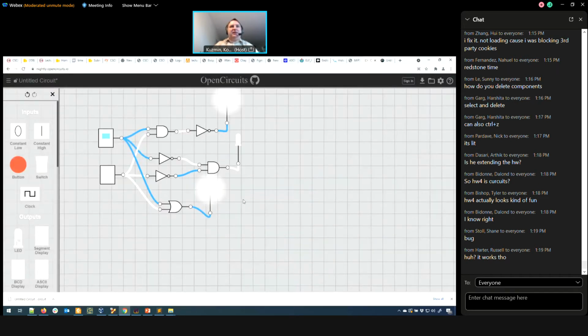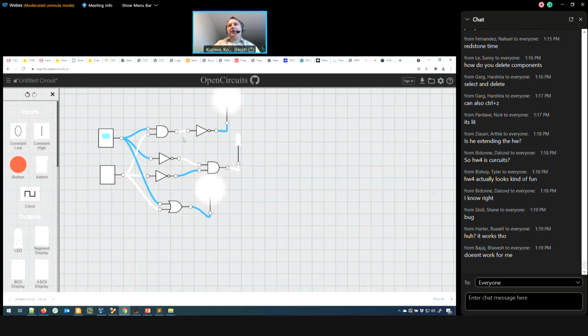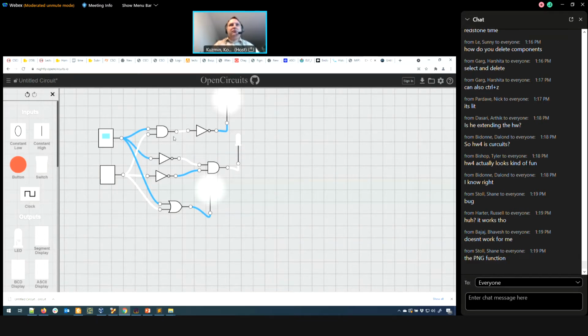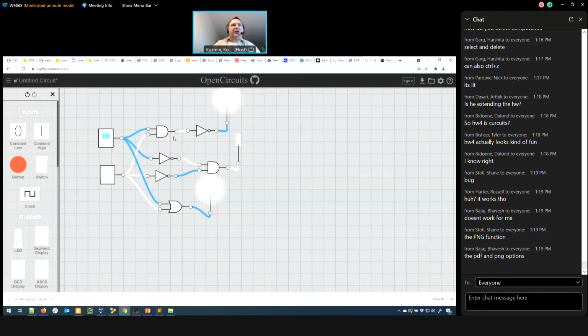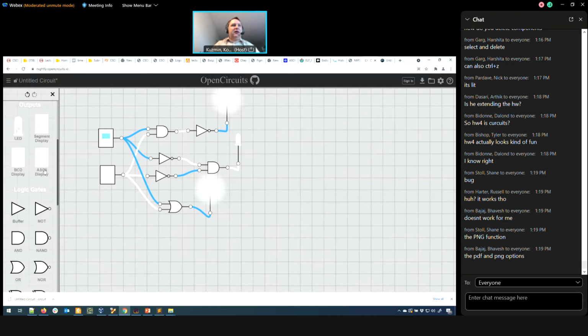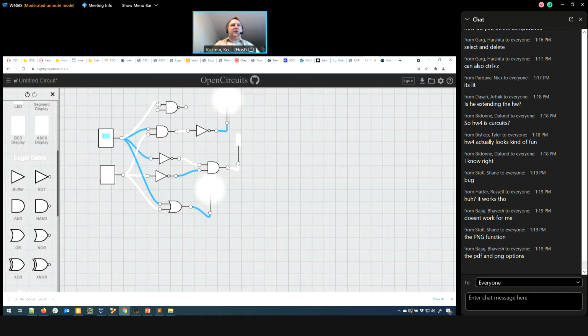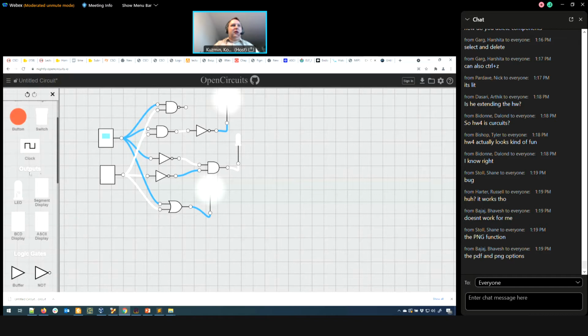All right, so that's it, and let's now look at the actual circuit that I tried to do here. This upper one is an AND with a NOT. So it's a NAND, and I can verify that it is a NAND. If I use this, wire the same inputs, and look at their output.